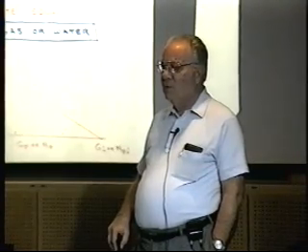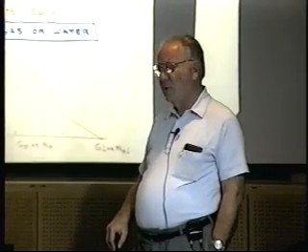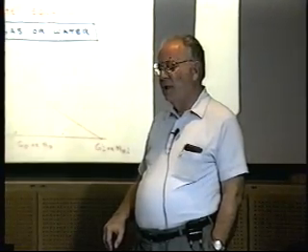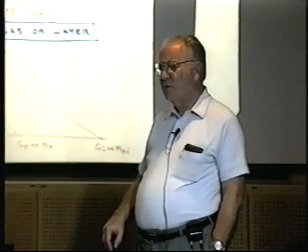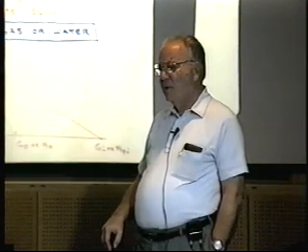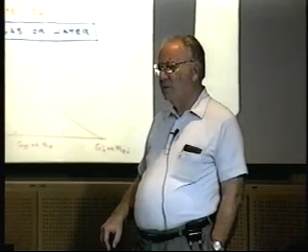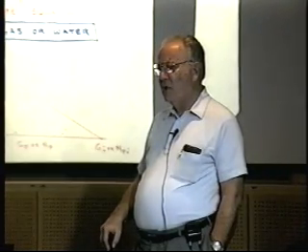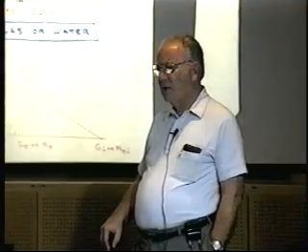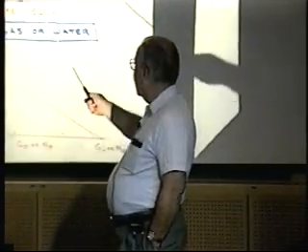Well, I don't know if we'll get to show that here now, but water flow is a function of a difference in pressure. The oil flow is a function of a difference in pressure squared. So there's a different amount of water that you're going to get with respect to oil for a change in flowing pressure, and you have to understand the difference in flow equations: delta P versus delta P squared.